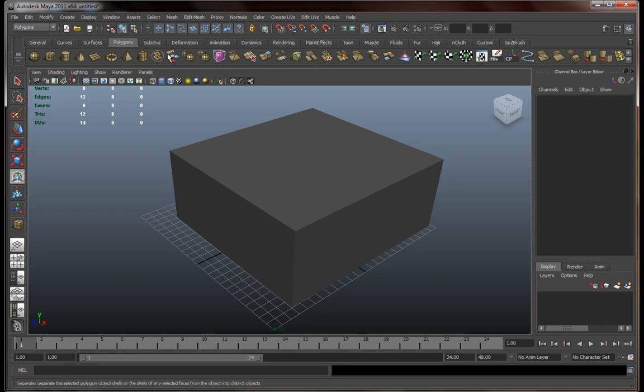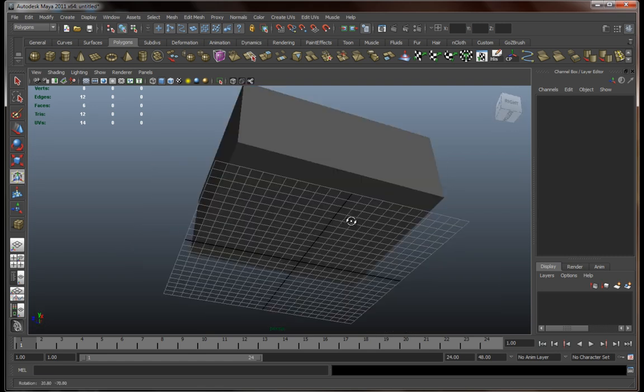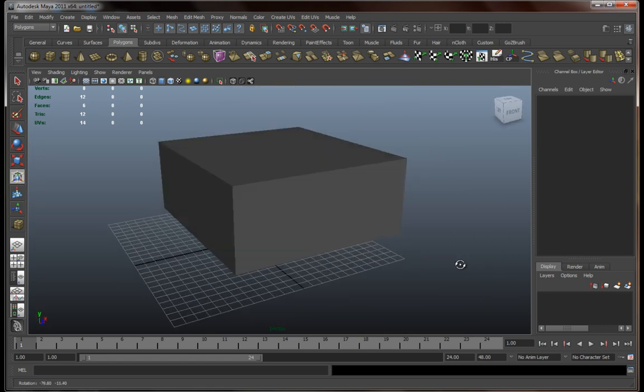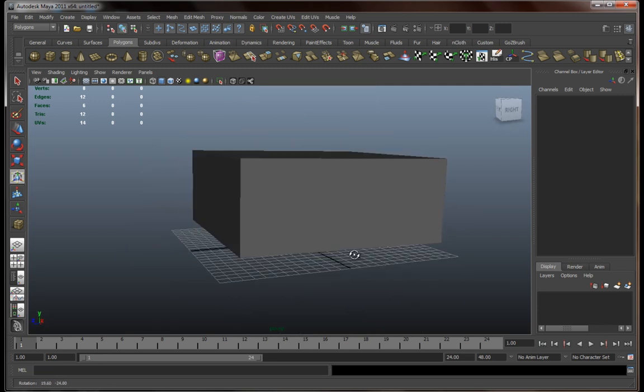From up here. Right, since we've finished with our manipulation and selection tools, let's see how you can actually move in your viewport. By pressing Alt and left click, you can move around your object, alright? Either to the left, to the right, up and down, whatever, go crazy, alright?